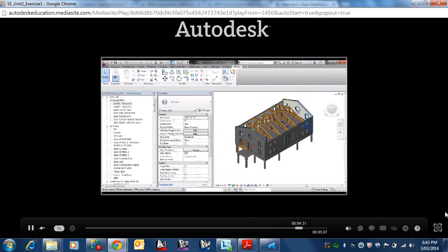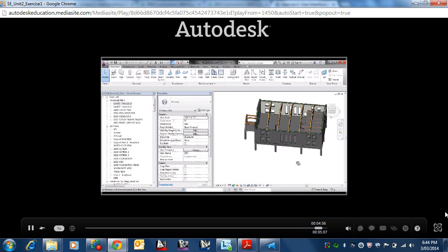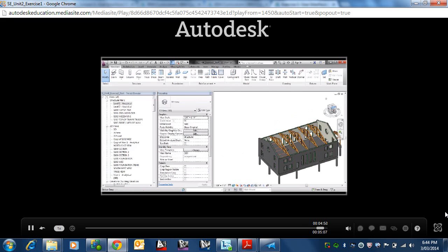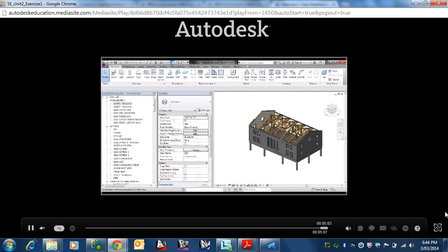In summary, most objects you want to model in Revit, you will find grouped within the various ribbons. And to see the amount of sheets, levels, and views that are set up, the project browser will provide you a convenient, quick way to access them. And to assess the information that's in a particular object, you'd have the property browser. And to navigate the model, you would most often use the view cube as well as zooming in and out, which is simply done with the mouse wheel. And this concludes this video.